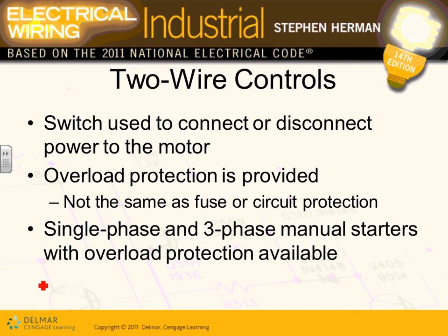When it comes to wiring, guys, there's a term that they use, and this is not new to you. It's called two-wire control. Here you're looking at two-wire control right here. You see that control turn the light on and off? That's a two-wire control. You interrupt the circuit that's going to the motor, and when you interrupt it, you have to physically, mechanically go there to turn it on.